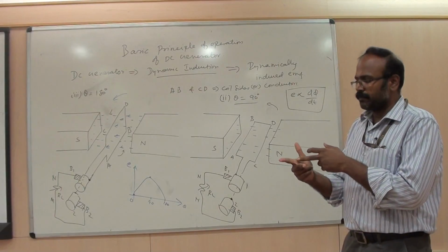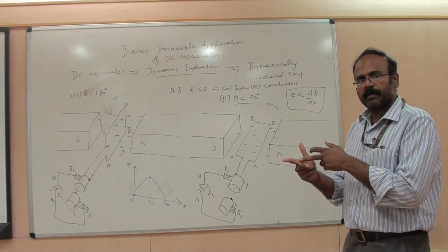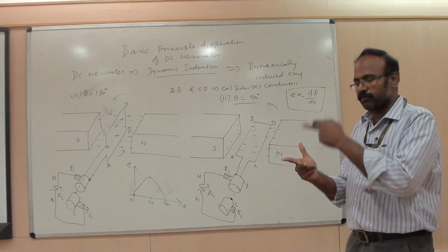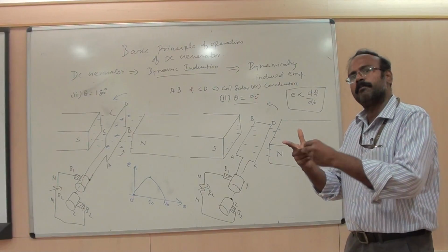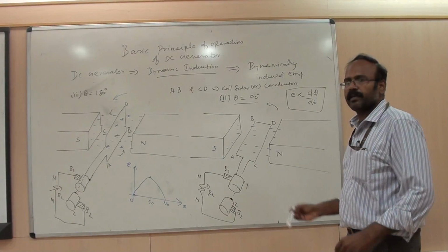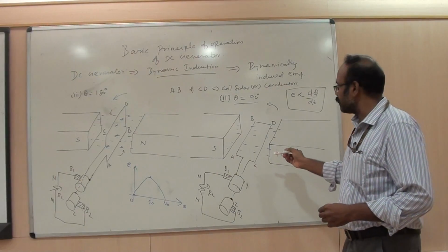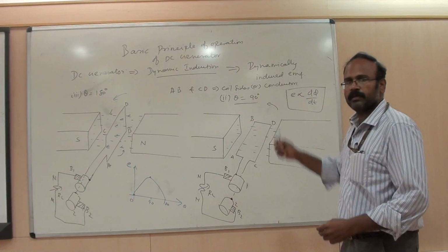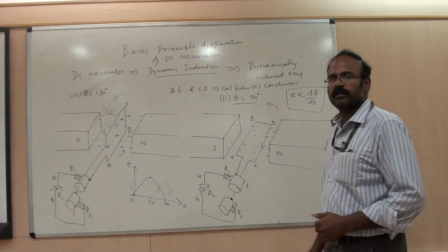As per our diagram, the magnetic field is flowing from North Pole to South Pole. If the conductor under the influence of the North Pole moves upwards, then according to Fleming's right hand rule, the current in that conductor should come out. Here, the direction of rotation is anticlockwise, and CD is the conductor influenced by the North Pole. When the total coil rotates like this, CD will go up. Thereby, according to Fleming's right hand rule, the current will come out from CD.